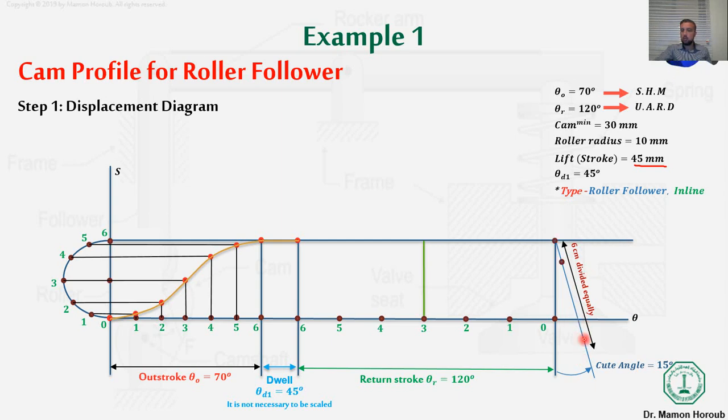And the last one, the 6th point, is connected with the 0 point, and then make parallel lines with the other dots. They will cross the vertical line in 6 pieces, and it will give you a perfect division of those 6 pieces. And then those 6 pieces are just shifted to the green line. The most important thing for me, which is the middle line, the green one, just shift those points to the middle line, and then number it from down 0, 1, 2, 3 until the last one, which will be 6.